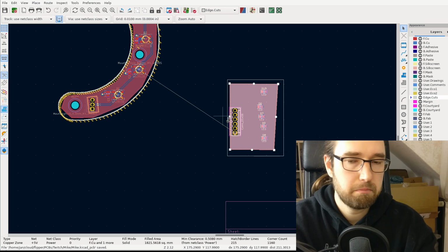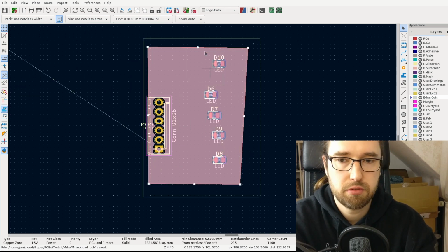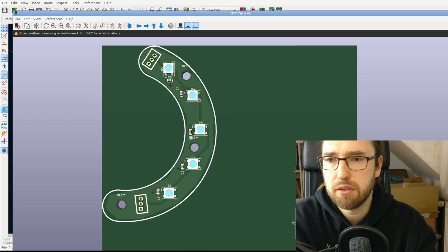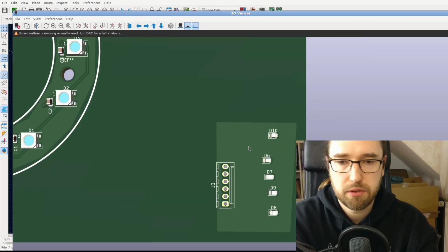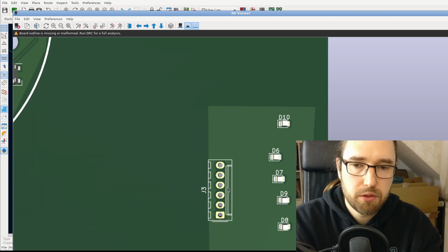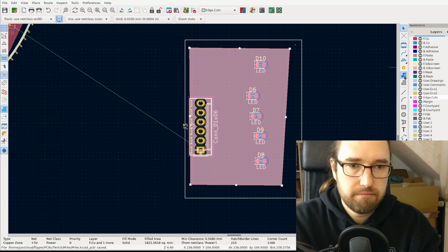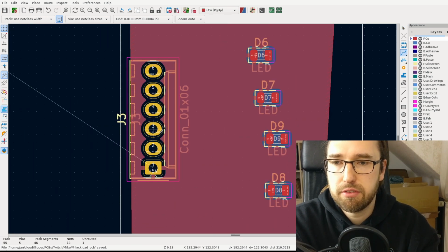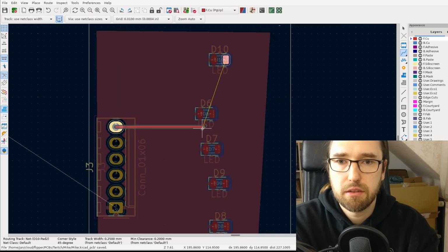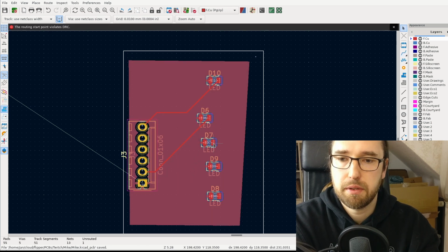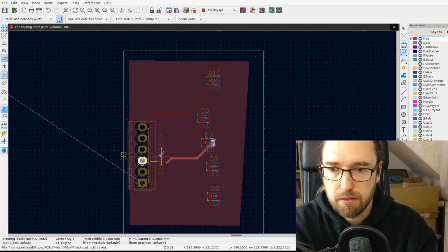This basically is a better conductor in my opinion. If you've got the plane, there's less resistance because there's more copper. So okay, now it does. Yeah, it cannot cut it anymore, so it doesn't matter for now, right? Now I got my ground plane here, and it's automatically connected to 5 volts. They are already connected. Let's say my layout is really like it is here, right? Now if I would want to trivially route it, this goes here, this goes here, this goes here.